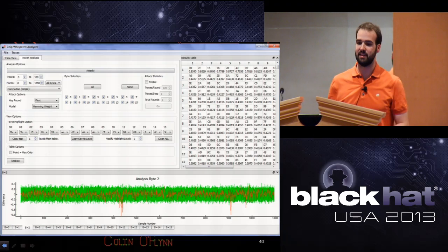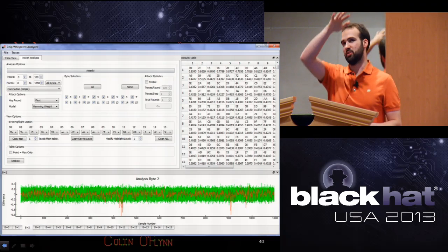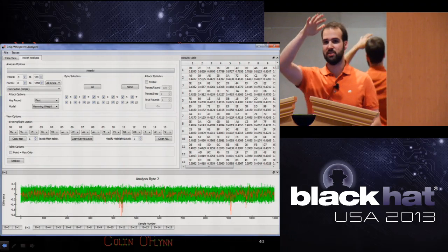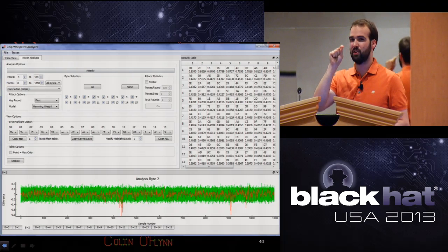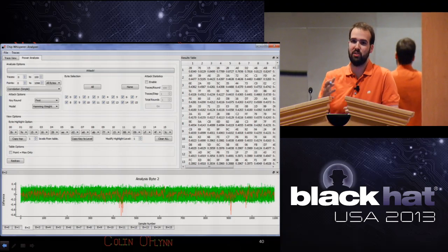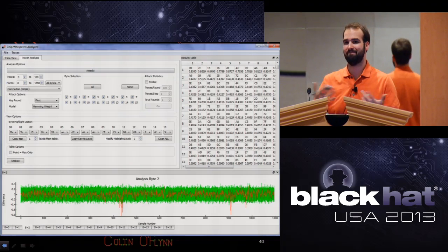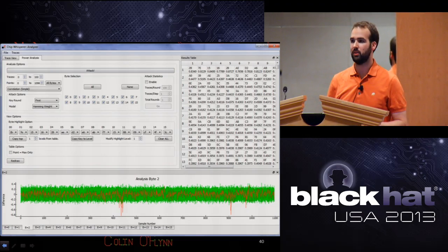The convenient thing is that there's only very small variations. For example, the encryption will do a bunch of subroutine calls that are all the same, and then a bunch of stuff that's all the same. At some point, the data differs, so the power is a tiny bit different. So you will still get really good correlation between the two traces because they're mostly the same, except for some point, and then they line up as usual.